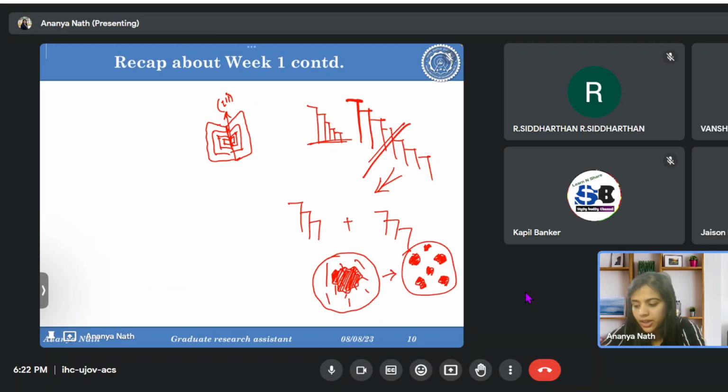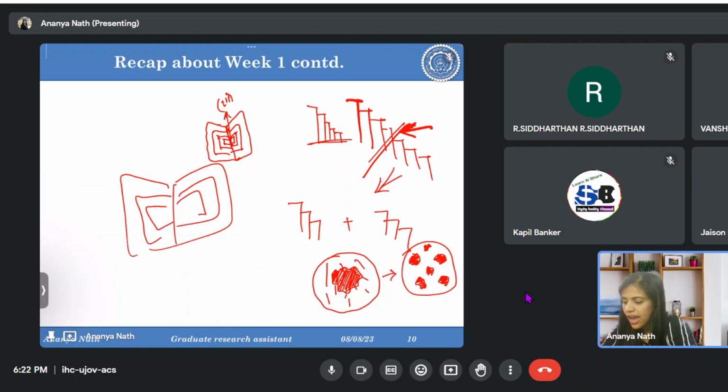These atoms get attached to the silicon which is growing, and after a few seconds, if the strontium has been attached to that silicon atom, silicon cannot grow farther because the strontium has been attached to it. So from the other primary silicons which are present inside the metal, the growth will start.